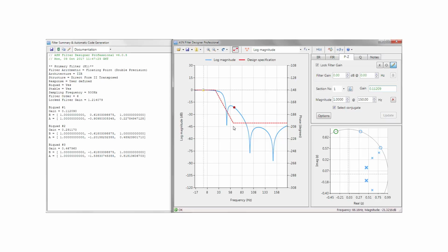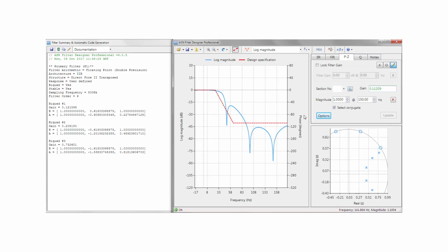Now, in order to deploy to the CMSIS library, we require that we re-optimize the design, as it's a mixture of different gains, and we have optimized the filter cascade manually. We need to re-optimize the design. That's easy enough using the re-optimize menu. If we click on biquad, the tool will automatically redesign based upon the specifications we've given. So seen there, you see that we now get exactly what we want.